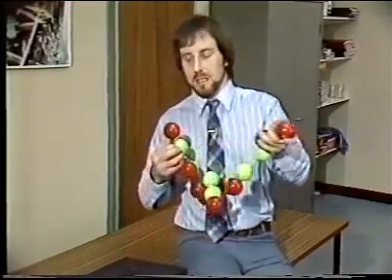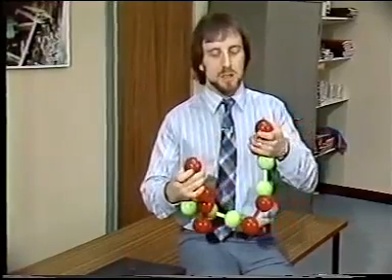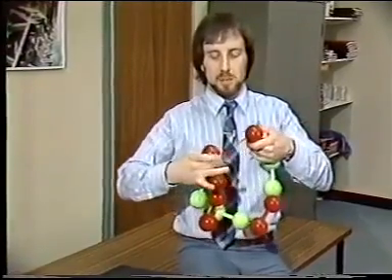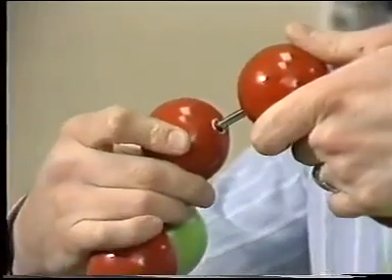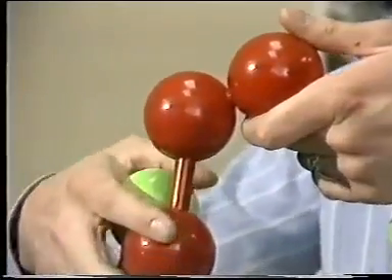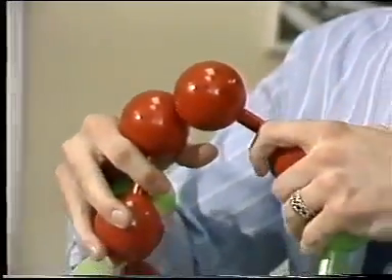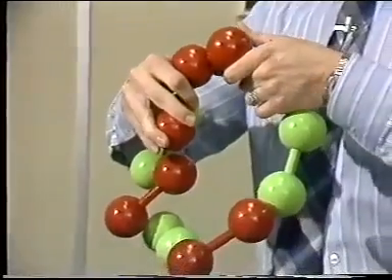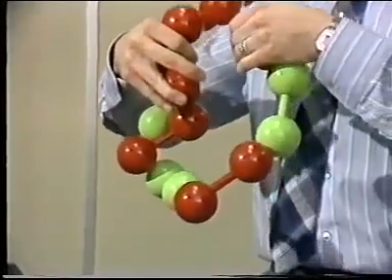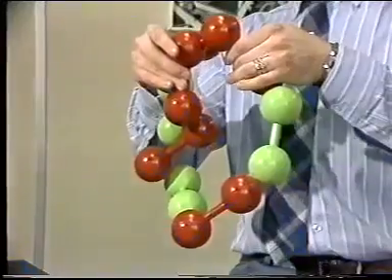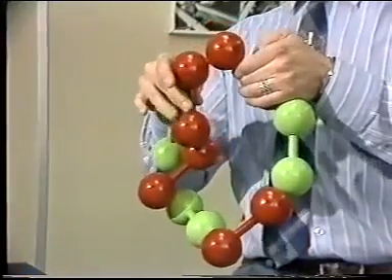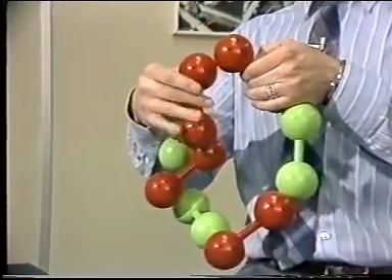If we remove this fixed link like so, create a new joint, connect it to the gripper here. So here we have the original fixed link. The kinematic structure has now changed, and the interchange graph has changed from a simple chain of 7 vertices to a closed chain of 7 vertices. How many degrees of freedom has this new system got? We've introduced an extra joint. You might expect it to have 7 degrees of freedom now.